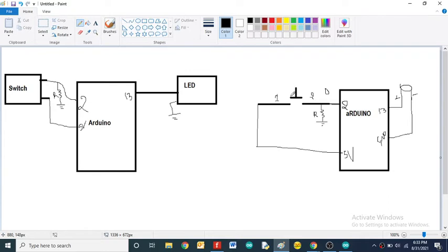When the switch is pressed, it is like this. This is a closed contact. Then your circuit flow will be like this. This 5 volt will be supplied to terminal 1 and go through this path because it is in the closed contact. Then it will pass to terminal 2 and to your Arduino pin number 2. So we'll get a high level on pin number 2.